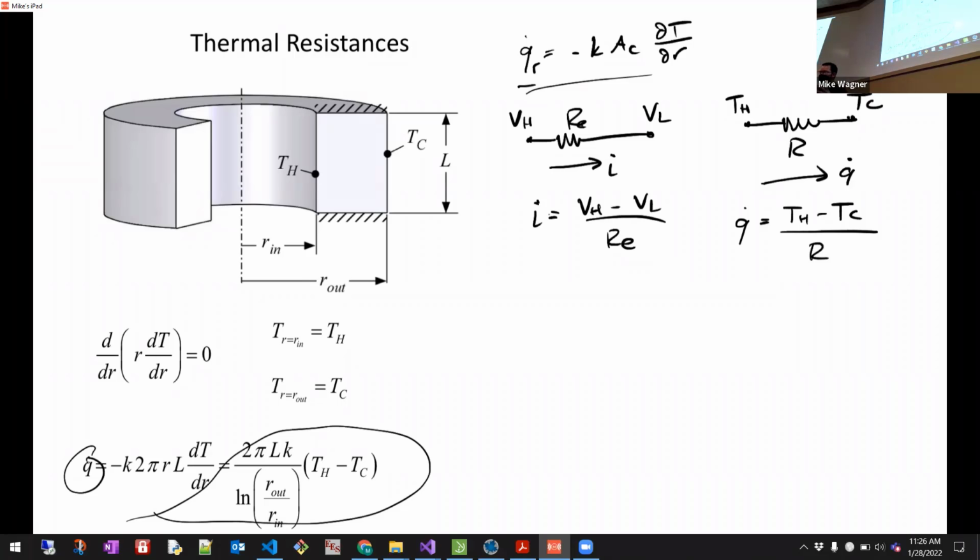We can say, for this conduction problem, I have a conduction R, and I have a convection R, and I have a contact resistance R. And what's the magnitude of the values of these R's? And just by looking at that, we can really quickly get a handle on what's important in the problem. Half the battle in this class and at this level is trying to figure out what's important and figure out how to deal with that.